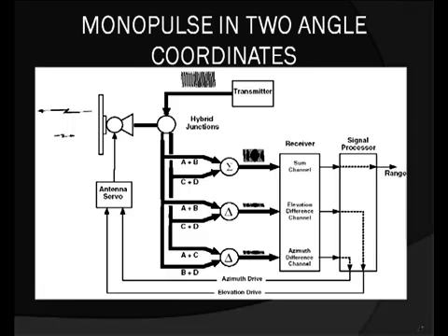One sum channel, the other one difference channel. In the context of this rat race, you can go with 1 and 3 as inputs, 2 and 4 as outputs, or vice versa.